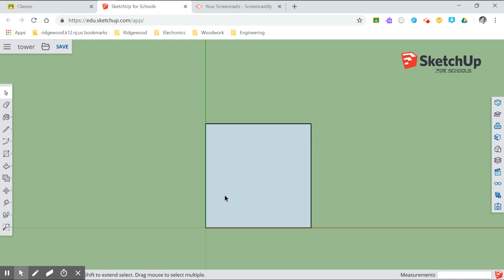Now this is important to understand because if I want to move this entire box, okay, I need to select the entire box to move it. So I need to either click away and draw a box that selects everything. So you see everything is highlighted. I can't just click in one location, expect everything to be highlighted. It is not. So if I click once here, I've only selected this face. I've not selected these edges. Okay, I've selected this edge, I've selected this edge.